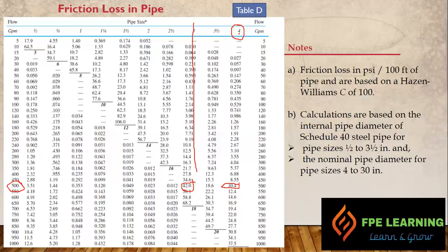Because if you are using a large diameter pipe, it's a waste of money. At the same time, you need pumping capacity. So the economics would not be handled in a professional manner. A best designer is one who uses economics, design and professionalism in his calculation to choose the correct size pipe for the correct application and the correct size of the fire pump unit, right? So with this table we simply find the frictional loss based on the flow and size of the pipe.